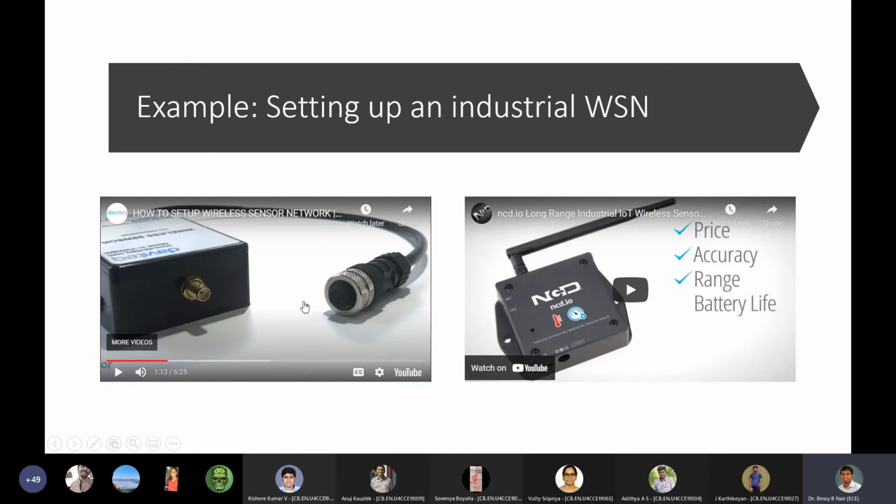And if the connectors are not matching, if you try to do mix and match, or if you put some converters, there could be signal loss and there could be issues with electromagnetic interference also. So it's always a good idea that you match the connectors before you purchase something. It is something very simple which people kind of miss in between, but it is a very essential part of the system integration process. You need to make sure that the connectors match. There are multiple different connector types, so be careful with that also.